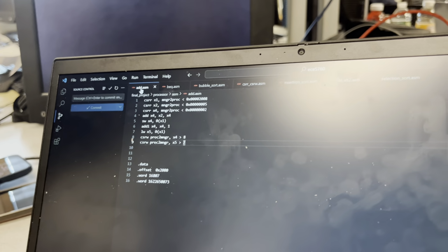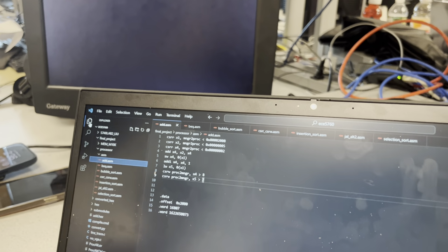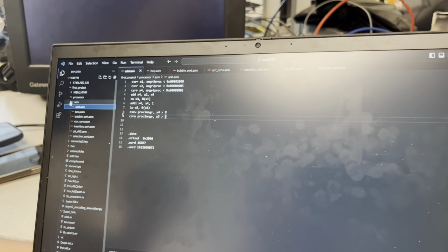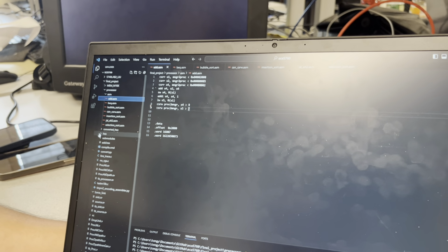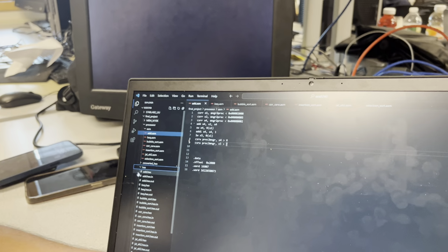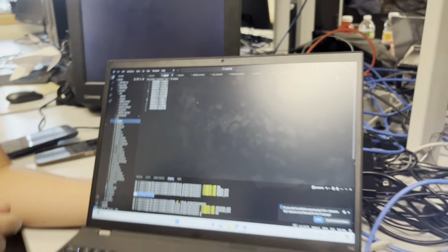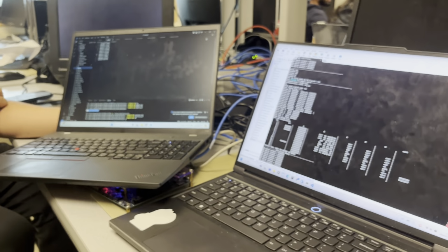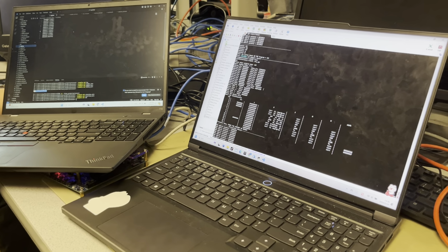This is the assembly code. It's a simple program which consists of a small number of instructions. First, some CSR instructions to initialize the register file, and then an add instruction. It will be converted to the hex file. How do you compile it? We use the Python script provided to assemble our instructions into these machine codes. And we can then load these codes into the memory from the ARM.